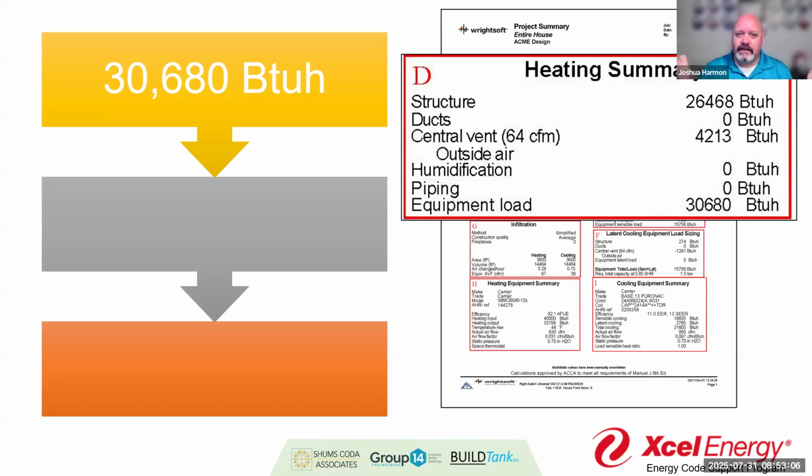If we're telling the mechanical design team, whether that's an actual engineering firm or a mechanical designer, or, I don't want to downplay it, an HVAC company that's doing its own Manual J calculation, and you've given them the wrong information, if they're operating under a belief that this building's envelope is going to have R21, but your REScheck shows R13, then that's going to affect how efficiently that equipment is going to be able to do it.